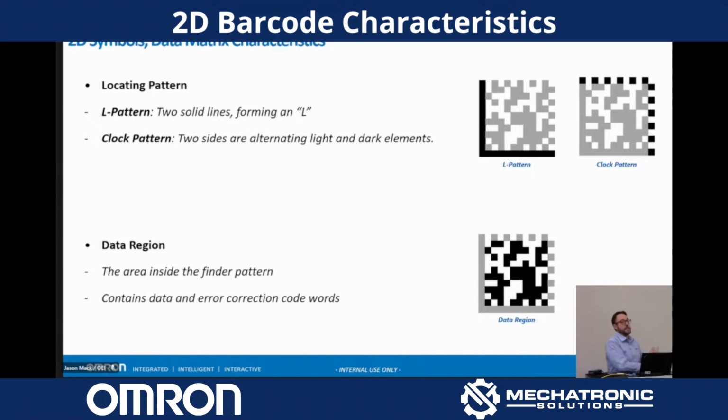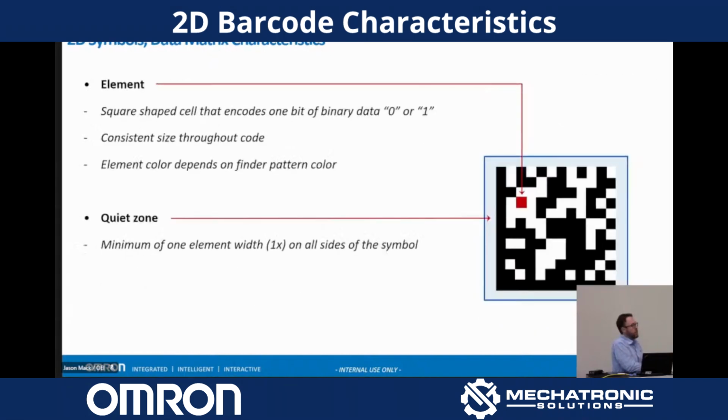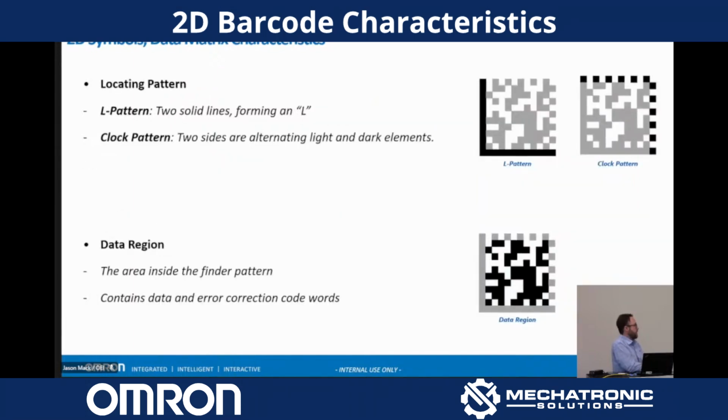And that's the basics of how barcode reading algorithms work, and we can get into how you can make that signal higher and the noise less, so we can encode data and then read it out more regularly. Everything that you see at the top, as well as what we showed around the outside as the quiet zone, that's all going to be considered the fixed part of the pattern. That term will come up other times, but that is fixed, and then the data, obviously, is the data region of the code.